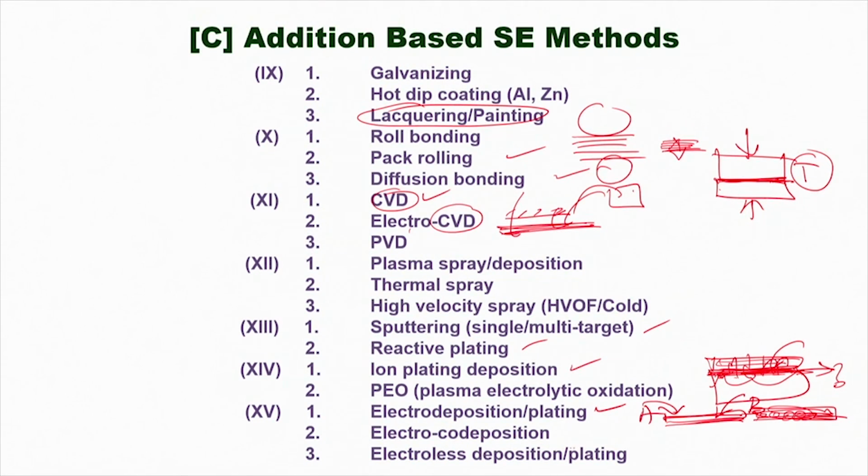You can also do electroless deposition or electroless plating, where the whole process is essentially because of a certain catalytic effect. So, if you have a bath and you dip a particular metal, without application of any potential difference, so there is no electrically closed circuit, yet because of the autocatalytic effect, the ions available in the bath will immediately tend to deposit onto it and form a coating.